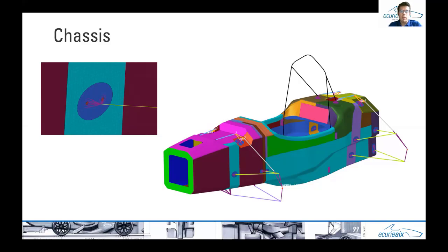With the corresponding material values from the steel we use for those two parts. We integrate them because they are main parts of the monocoque, and they also stabilize it quite a lot. We also simulate our monocoque every time for torsional stiffness, which means that we fix the car at the back and twist it in the front.